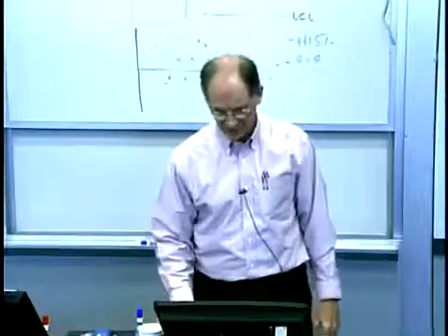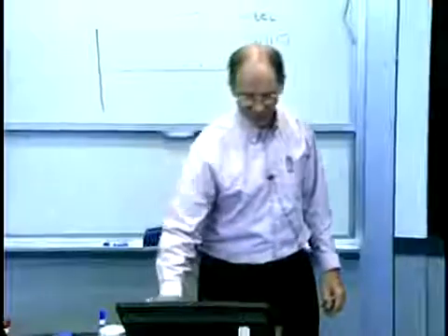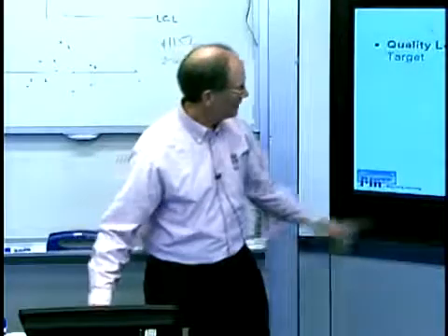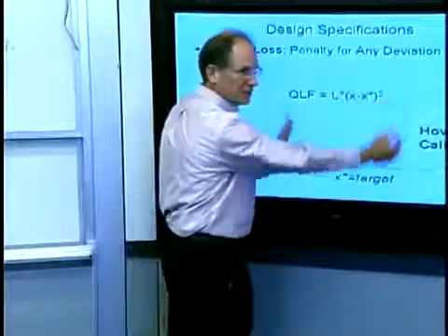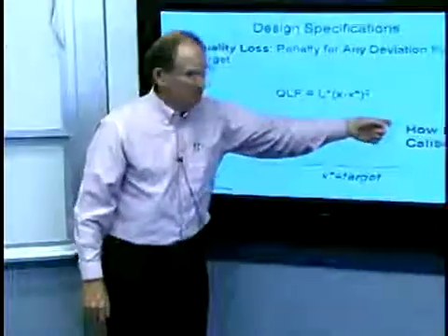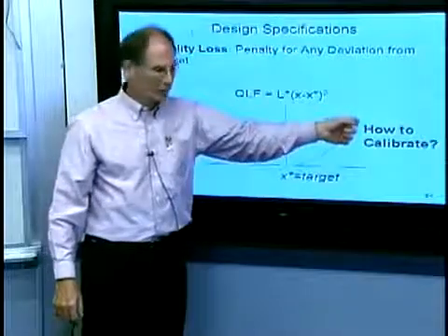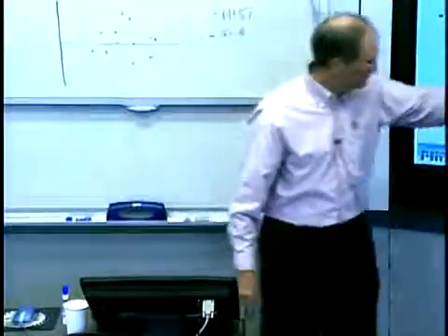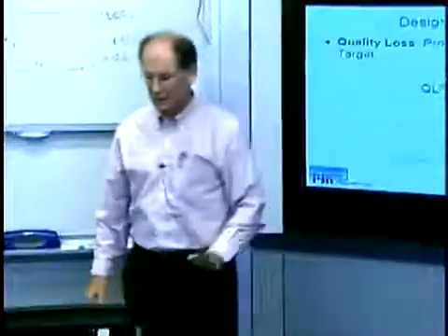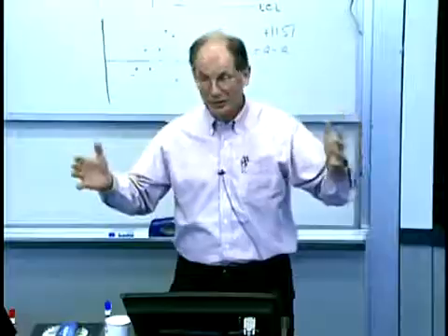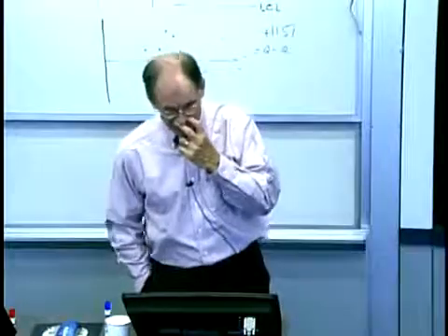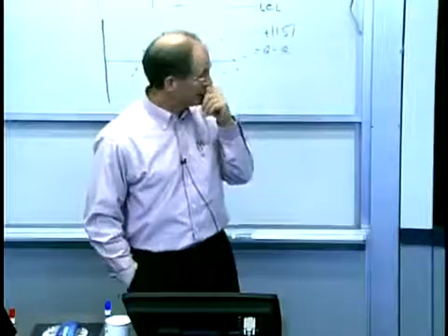And there's a simple way to calibrate this. If I actually have upper and lower specification limits here, I can say, what's the cost of scrapping a part? And where this curve crosses that, you say, okay, that's my calibration constant. But again, there are some great case examples that show that if you work against quality loss, once you combine parts together into the whole thing, you actually end up with a much better overall quality. But for the moment, let's just look at the tolerances.